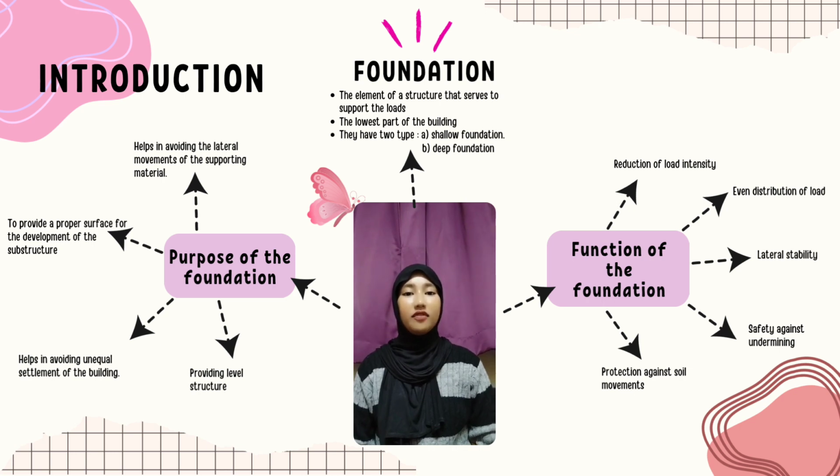Then, a designed foundation helps in avoiding the lateral movement of the supporting material. After that, a proper foundation distributes load on the surface of the bed uniformly. This uniform transfer helps in avoiding unequal settlement of the building. Differential settlement is an undesirable building effect.